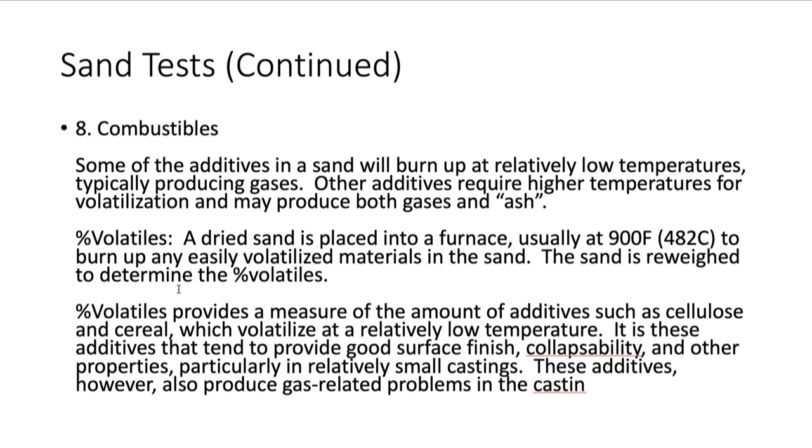So basically, the sand additives burn up at a relatively low temperature. Combustibles is usually at 900 degrees Fahrenheit. And volatilized means that it might have some chemicals in there that come off as you heat it. So when we volatilize it.